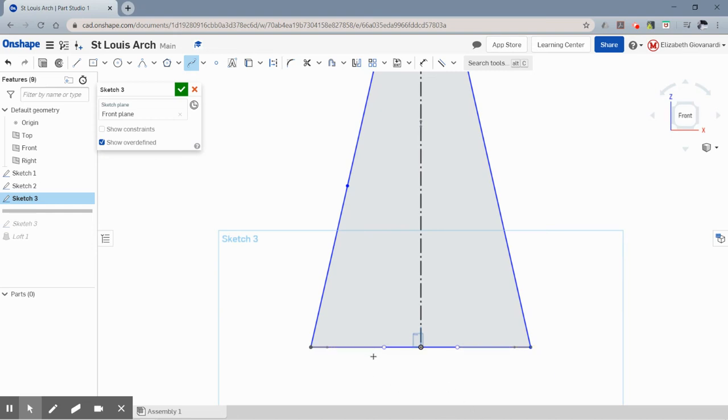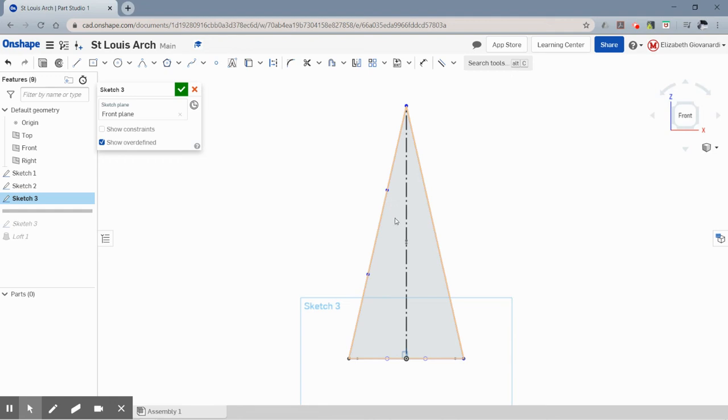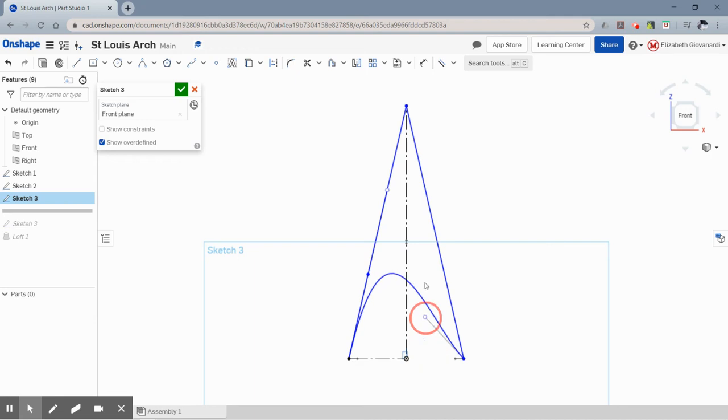And so now it doesn't look like much happened, but I actually have a spline here. And its vertices, basically its control points, are here and here. And the point of doing that, this arch here, or this 3-pointed line segment, is so that I can drag this control point up and put it right in the middle there. And now I'm going to drag this point up.